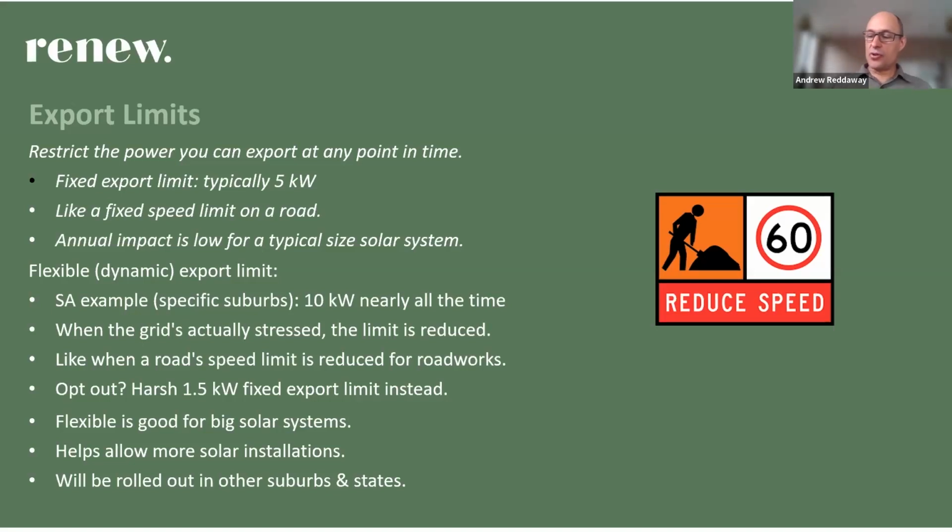Now, the company that owns the poles and wires in your area, so that might be like Jemena or Powercor, would be the main ones in the main catchment area for this webinar. They are going to put some limits on how much electricity, how much power, you can push into the grid at any point in time. Basically, because their poles, wires and transformers and stuff can't handle all the houses going at full power on a sunny Sunday with mild weather. That can overload their grid.